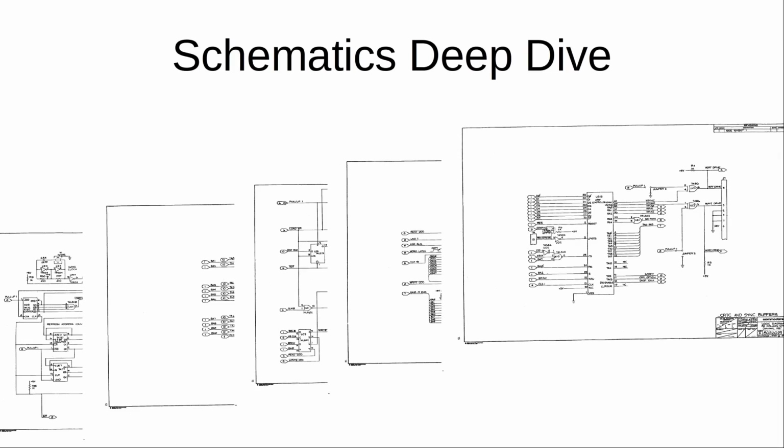What we should also not forget is that the 8032 was first, and that was a purely 80 column model, and then Commodore modified that board into what is called the so-called universal boards. I may have mentioned it before in that video. Those universal boards have the option to be used as a 40 column 4032 model or as an 80 column 8032 model. And they did this with a number of jumpers and parts options, where you can leave out a number of parts from the 8032 model, change some jumpers, and then you actually have a 40 column model.